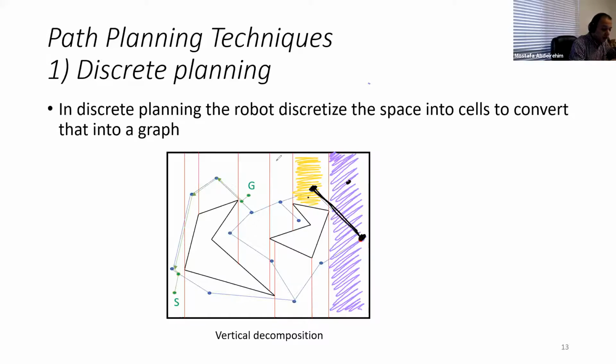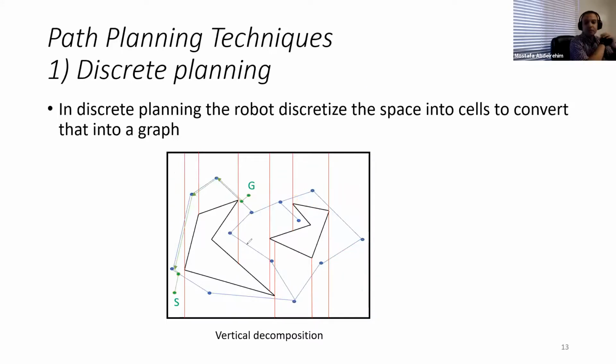So we have also here another area, this area here, okay? We have another area, this area here. And for each area, there is a point, until we construct a graph. This graph that you can see here. This graph is your map for this entire environment. So this is your environment now, okay? And the robot is sure that if it moves on any of these edges, it will not hit any of the obstacles or, of course, the wall in the environment.